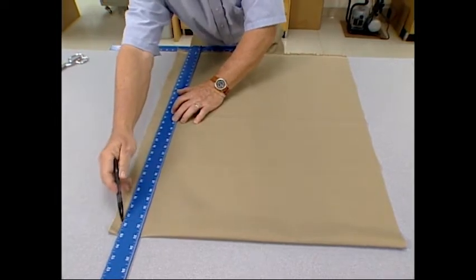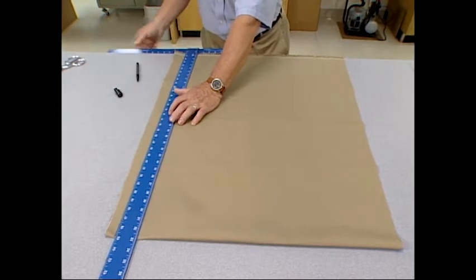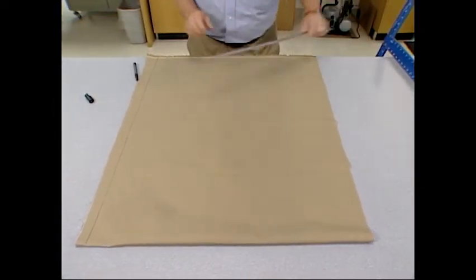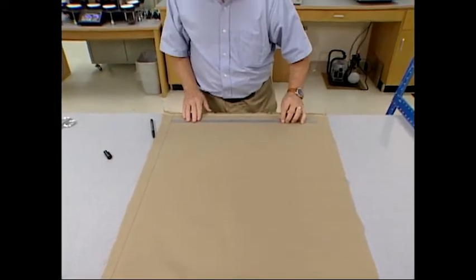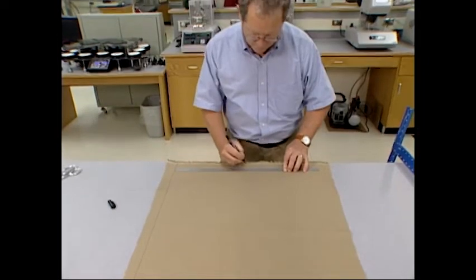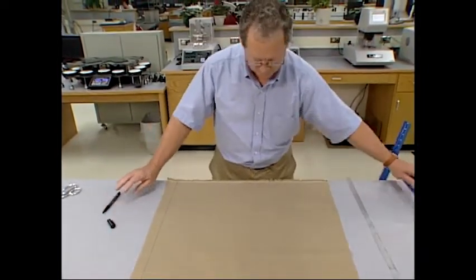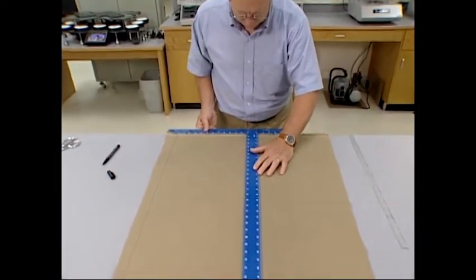From each roll or piece in the lot sample, cut, don't tear, at least one laboratory sample the full width of the fabric, and at least 250 millimeters, 10 inches, in length. The cut edges must be a straight line, free of indentations or bulges, and parallel to each other. Measure the length and width of the conditioned specimen by a suitable measuring device.